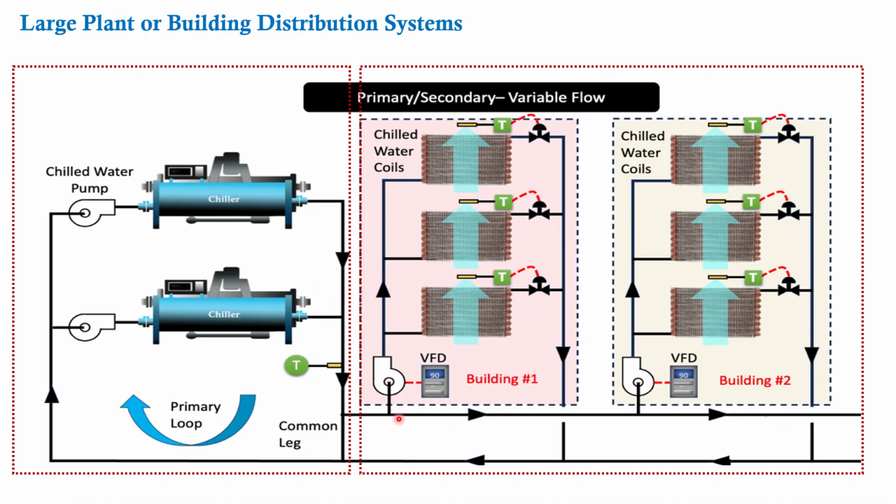Now in this, what we are doing is locating the pump at that particular building or the load wherein the load is going to be. It is good to have for buildings which are big in size. For a small building and application, I can have the secondary pump over here. But if the capacity is bigger, the load is going to be bigger, and the nearby AHU or load is going to experience more chilled water pressure drop, and the valve performance is also going to be deteriorated. So in that context, the distributed pumping system becomes more viable and a good option to evaluate.